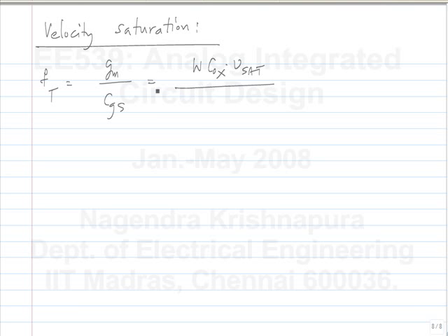And Cgs is again the same thing. So it is not inversely proportional to L square anymore, it is inversely proportional to L. This is the reason why when you go to very short channels, you do not get an L square improvement. When you go from, let us say, 0.18 to 0.09 micron technology, you do not get a 4 times increase in speed, you will get something between 2 and 4.